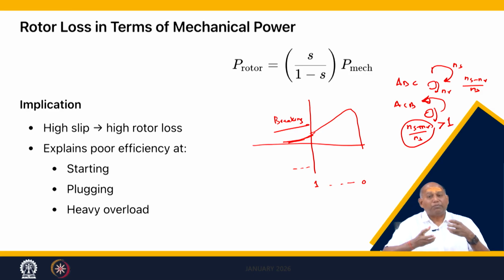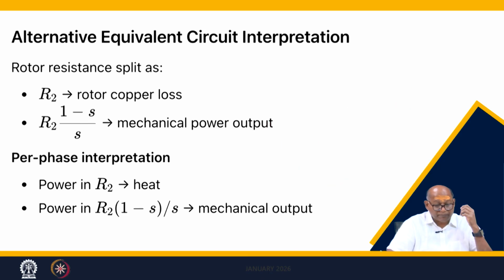So the motor starts, but it cannot rotate because the torque required is so high. Once it cannot rotate, it draws more current, because slip is equal to 1, there is more loss and more heating, and finally the winding burns out. Therefore there is a lot of protection for this, such as bimetallic relays, for switching off when the current or the temperature is high.